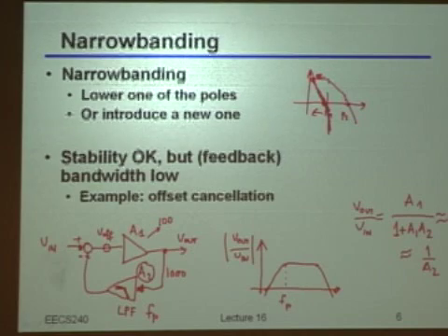Yeah. Is that V out over V in at DC on the right there? The expression, you mean? Yeah, okay, even if A1 and A2 are a function of s, you can still write it. But you can assume, for instance, DC and reason about that. And so what you notice here is that indeed, if A2 was infinite at 0 frequency, I would have a complete nulling of the offset. So potentially an integrator would do the job, right? If it could be possible to have ideal integrators.